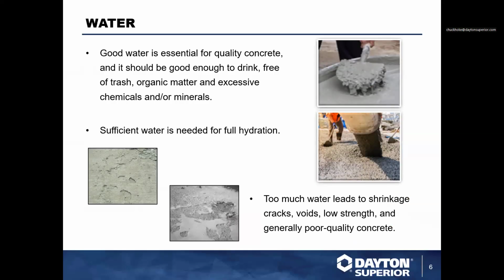I don't care how good cement you have or how good aggregate you have or sand you have, if you do not have good, clean water, that is the essential component within this product mix. The water actually hydrates the cement. By hydrating the cement, if it fully hydrates the cement, you're going to get full strength out of the requirements of what that cement was designed to hold and to actually do. So you need to have enough clean water for sufficient hydration.